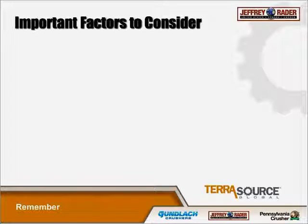A few things that are pretty important to consider: you want to try and keep the blower located fairly close to the feeder. It's possible to have the blower far away. A lot of times that's the only scenario, and in that case we just need to know the piping routing from the blower to that feeder so we can calculate the pressure losses from the air.